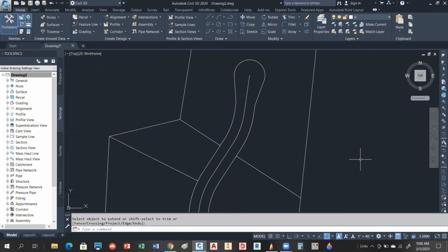Everybody okay with that? So when you're in the trim command, when you hit the shift key, it does the opposite. Yeah, and when you say you hit it, you have to hold it down. You can't just hit it, because if you just hit it, you're back. So if you're in trim mode and you hold shift, you're now in extend, and vice versa. If you're not used to that little thing, that's not a Civil 3D thing, that's an AutoCAD thing. But hopefully you're seeing we're utilizing combinations of both, and that's the really cool aspect of this. Yeah, that and that lengthen tool that you used, those were good. And that's AutoCAD, really.